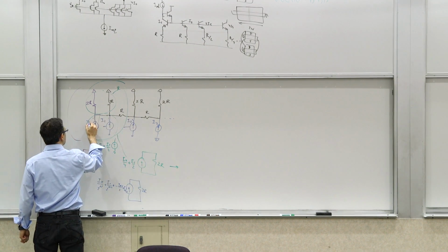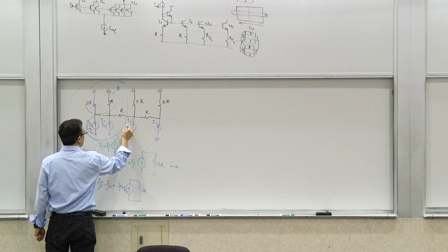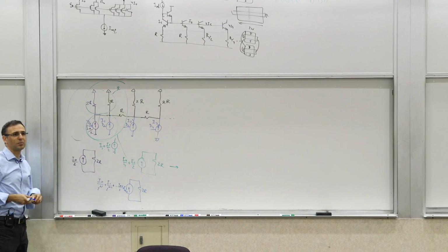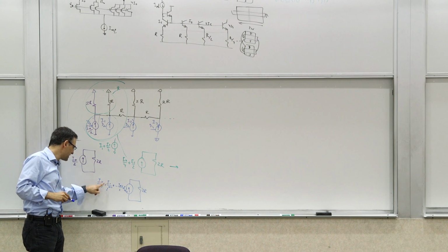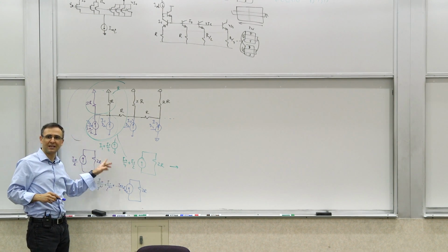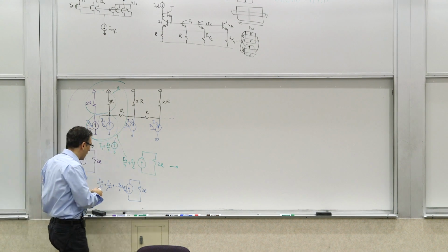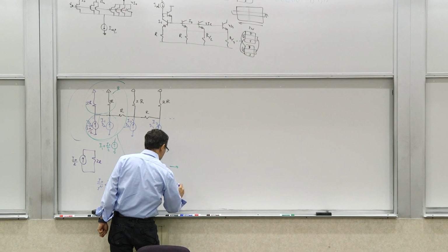And apply your D0, D1, D2, D3, your digital bits, to these current sources. Whether or not you turn them on and off, they would have the base value, so you can make them all equal, and then turn them on or off. So the overall response would be D0 times I0.